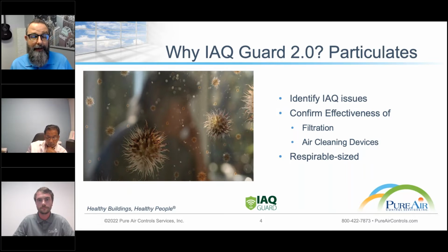So you would expect to have a lower particulate load in rooms with this new air purification technology. But if the particles remain unchanged or even start to increase, then that might indicate problems with the equipment, that the filters need to be changed. These kinds of issues we're going to take a look at.